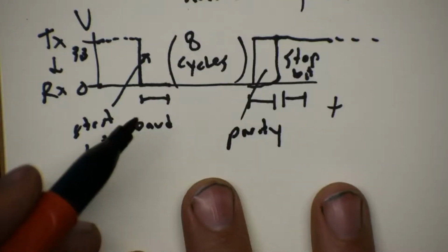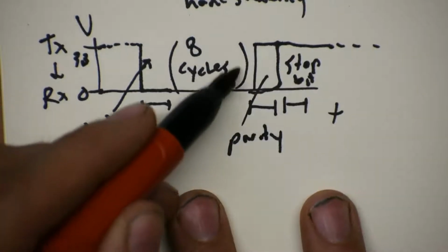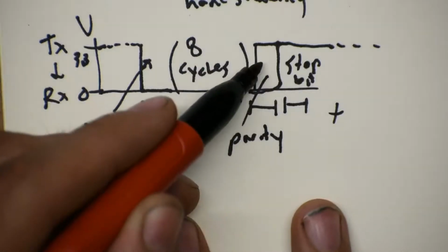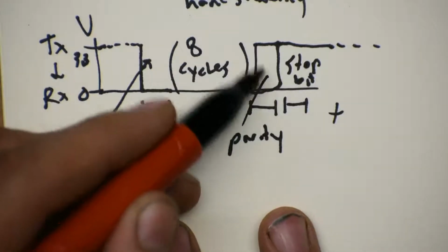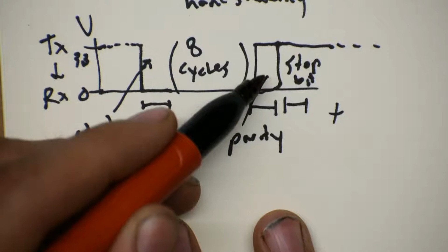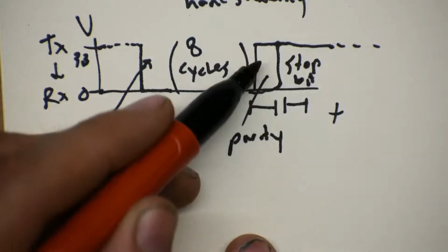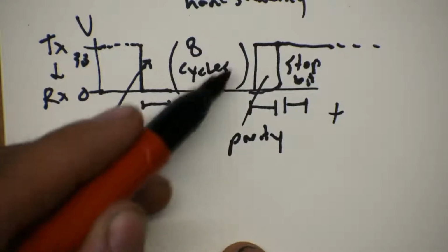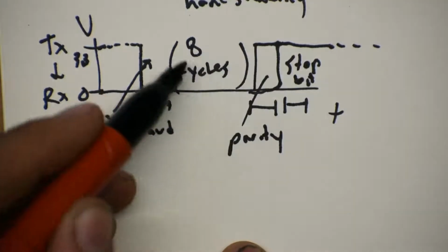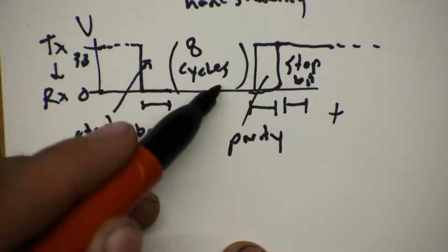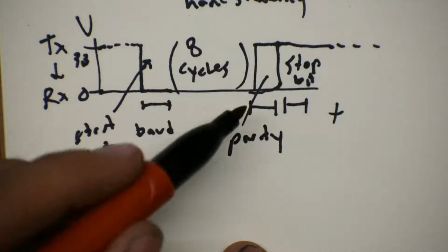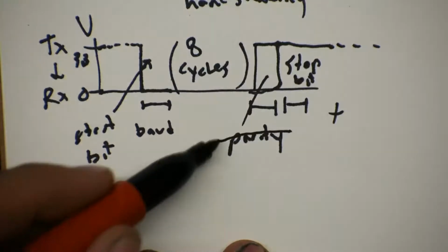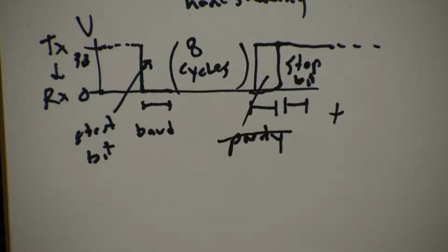So one way to do error checking here is that you sum up the 1s and 0s in the byte that you just sent, and whether it's even or odd gets a parity bit, and so you get a 50-50 chance of your parity bit not being corrupted. If that parity bit doesn't match what the parity computation is, you should throw away this byte. So we usually don't worry about this. So we turned off the parity bit when we initialized the UART.